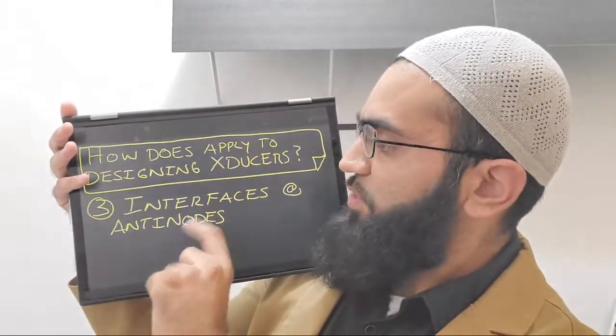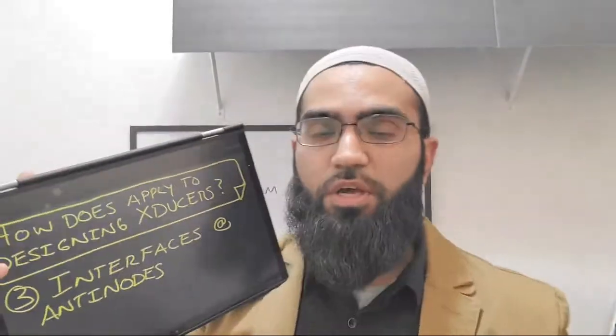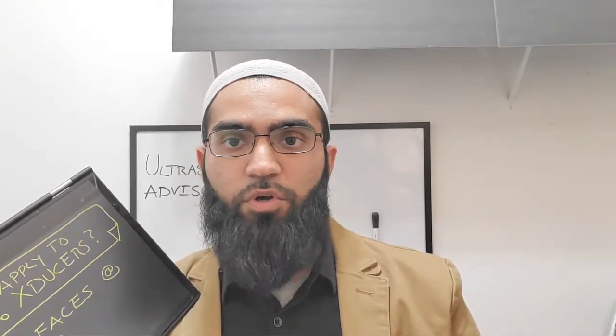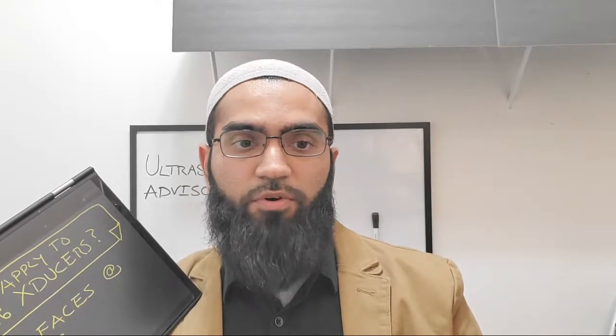So also, interfaces should be at antinodes in order to maximize the power transfer and allow you to operate in higher power operation. Otherwise, you'll have a stress concentration at your component interfaces that's going to lead to nonlinearity, loosening of that tool, and other unideal behaviors and characteristics.